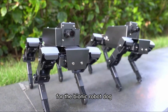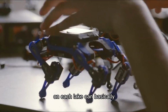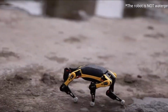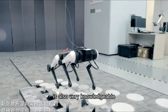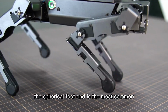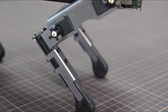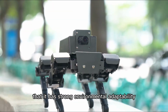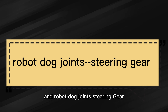For the Bionic robot dog, the 3 degrees of freedom on each leg can basically meet the requirements of reaching various positions. The design of the foot end in the robot dog's leg is also very knowledgeable. The spherical foot end is the most common design for quadruped robots. The advantage of this design is that it has strong environmental adaptability.